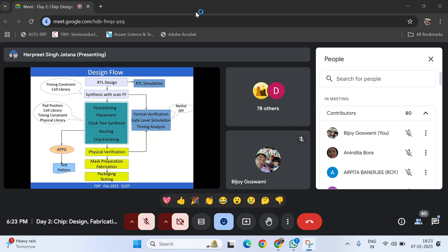Because the substrate is the same, the noise is coupled to the analog. The frequent high speed change of any digital input can be coupled to the analog, thereby creating some noise there.